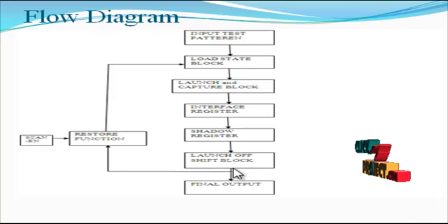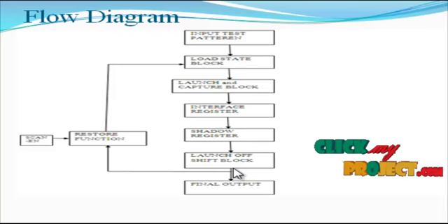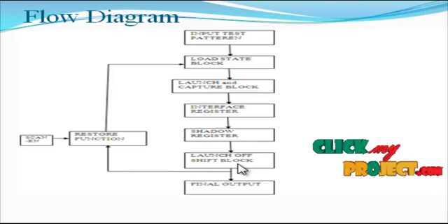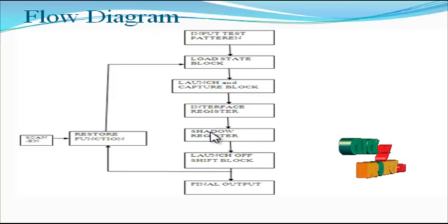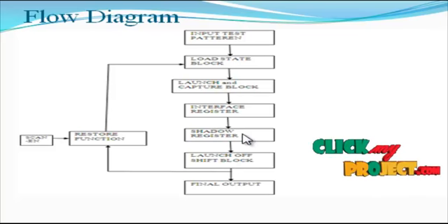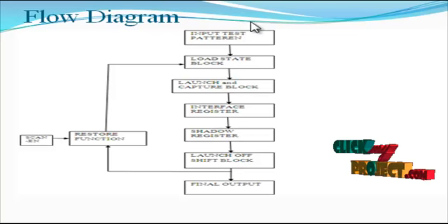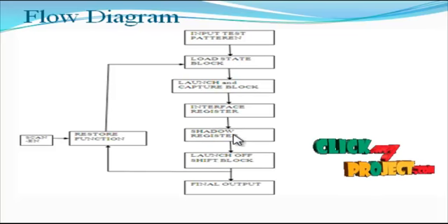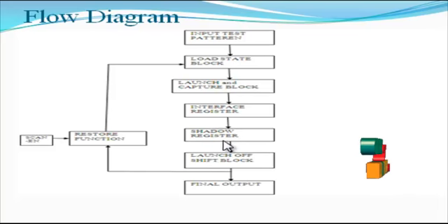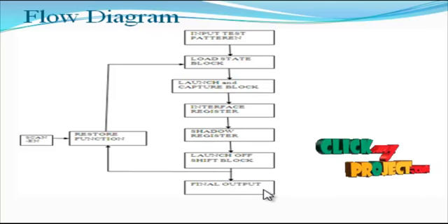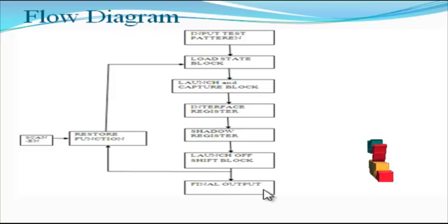This launch and shift operation is activated by the scan input signal. The scan input signal is set, and the launch and shift operation is processed. At the same time, the shadow register applies the last bit and compares it using the XOR gate function. Then the expected input is processed and the scan input is applied, thus the two inputs are considered, and finally we calculate the fault detection and the output is calculated by the synthesis and simulation results processing.